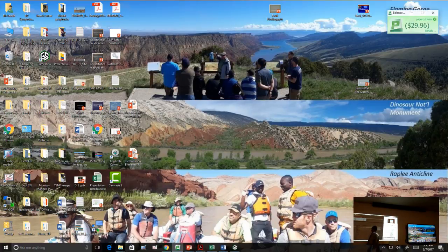So what we're doing here now is there's a set of applications, different types of tasks that you can do using this software. We don't necessarily need to launch all of the functionality of the application, so we're just going to choose a couple right now. The instructions have you click on GIS, and if you hold down your control key, you can select others: well log correlation, and seismic interpretation. So we're going to choose those 3, and they're highlighted.